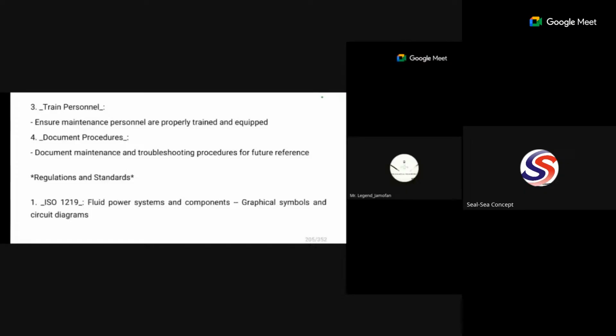It's very important. The procedures that should be followed should be documented so that it will help every personnel that wants to work on it. Okay, what are the procedures? Do you have to open this place before you loosen this place? Do you have to close that place before you open this place? Those are the procedures. It should be documented. It shouldn't be something that you believe the person performing the maintenance should just know. No, there should be documentation about it.